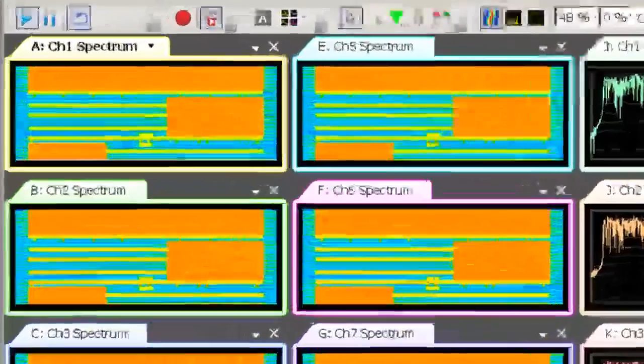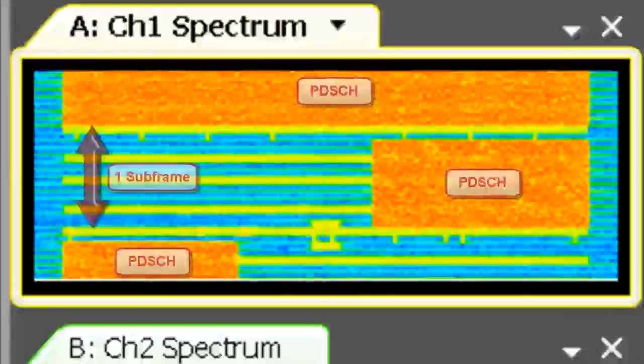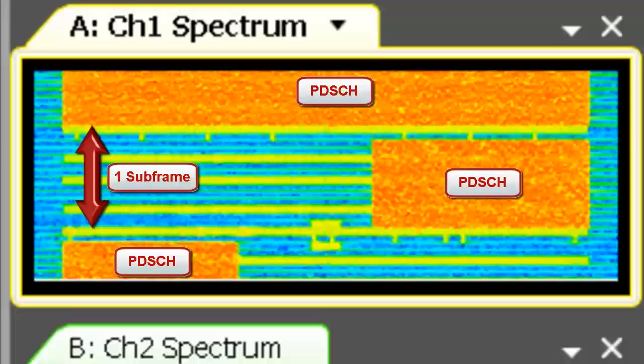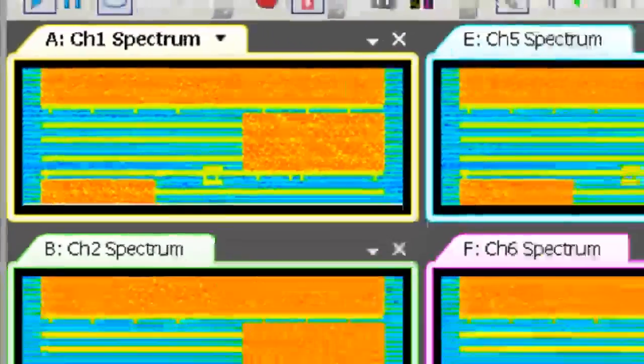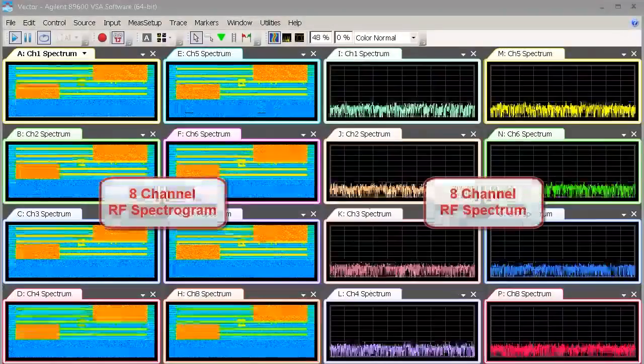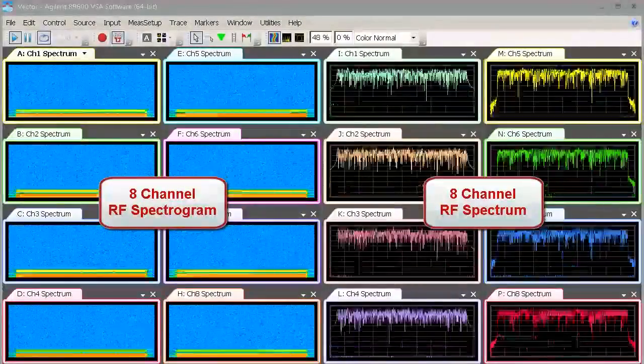This allows us to quickly build up a picture of per subframe RF activity levels for user-specific resource block scheduling as well as common control channels and signals. Note this feature does not require any demodulation at this point and is a very useful debugging tool when investigating unexpected RF or scheduling issues, especially when those issues impair normal demodulation of the signal.